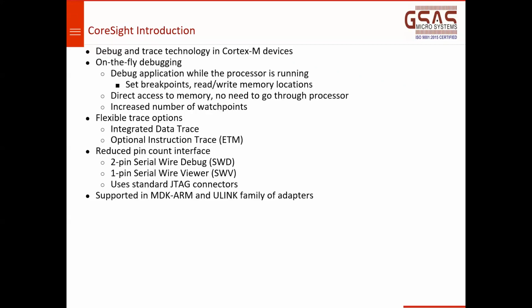And what does this on-the-fly debugging do? When you're running the processor itself, we can set a breakpoint, we can modify the memory contents, we can change the value of the variables.